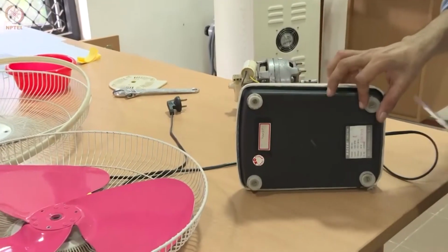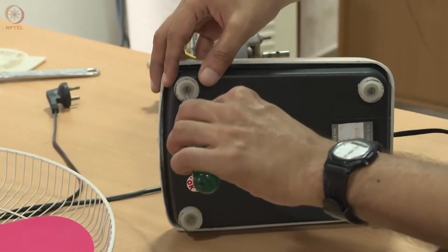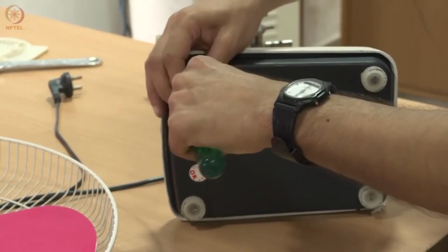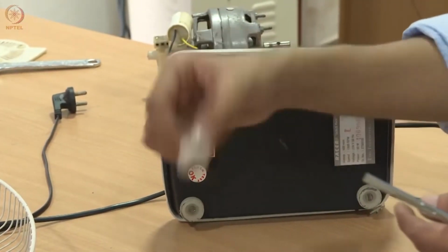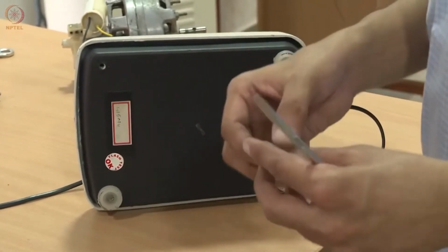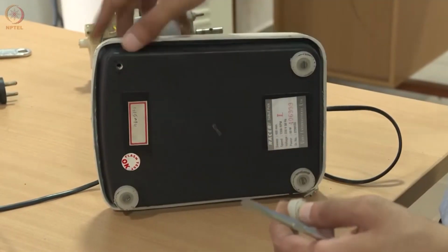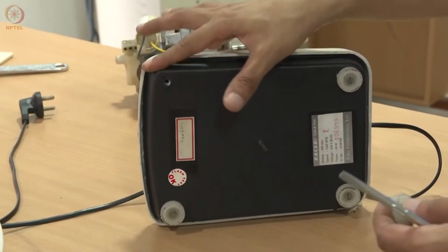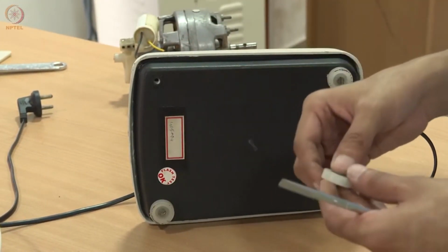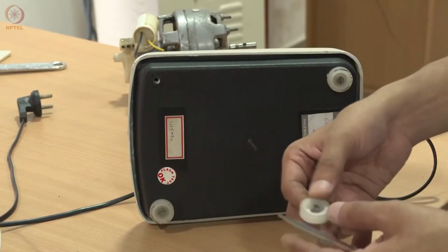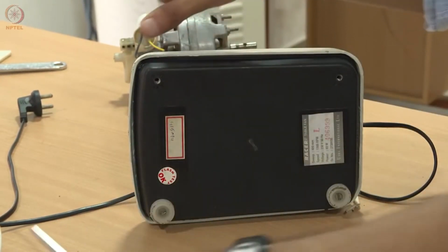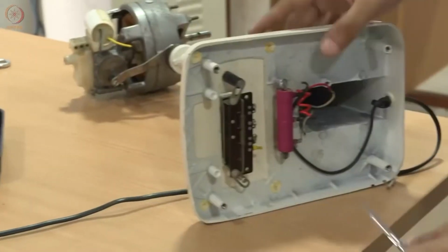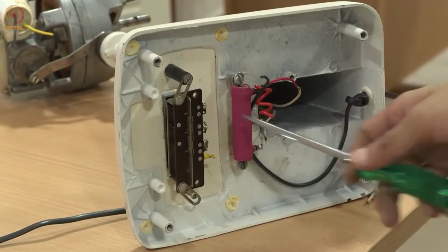So now let me dismantle the bottom part of the fan. Now keep in mind this is a slightly older version. So the newer fans have slightly different construction. So these are bottom bushings, and then they are held in place by screws, and the screw that holds this also holds the cover in place. So basically this is how we can reduce the number of components. So newer fans basically don't even have bushings like this. They have what is called press fit bushings, where you can just press them in place. Now this fan has been used many times, so the electrical wiring is all disconnected.